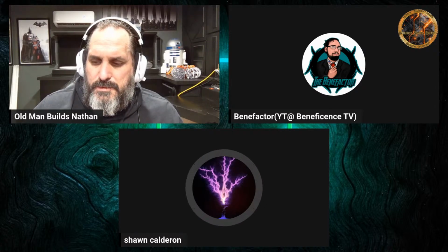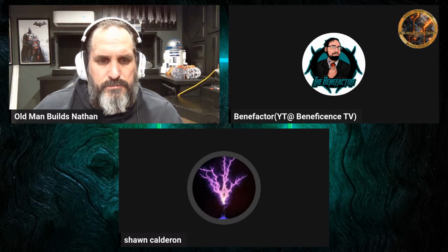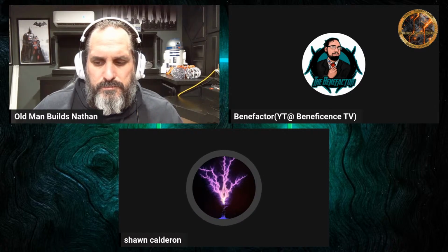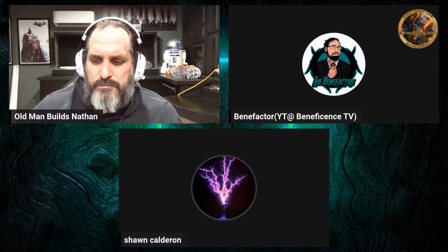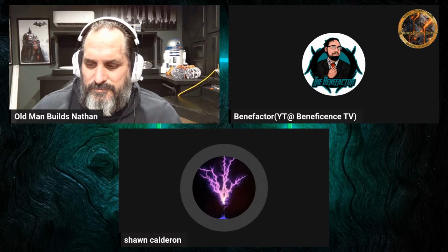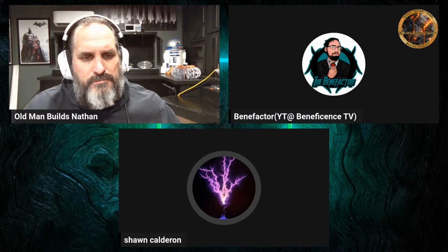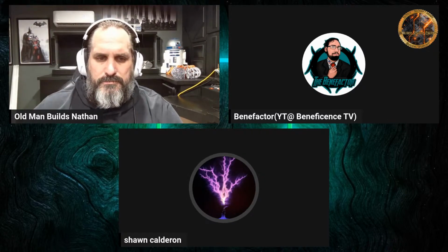We got John Curley. When making a high voltage capacitor, you may need to have a significant dielectric border around the plates to keep from arcing over. Yeah, that's a really good point. My thinking is not using it for higher voltages than 1,000 volts. The reason for that is the output of the ZVS oscillator is only in the 600 to 800 volts range.